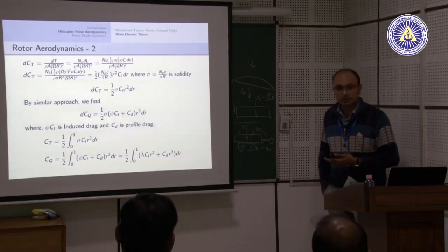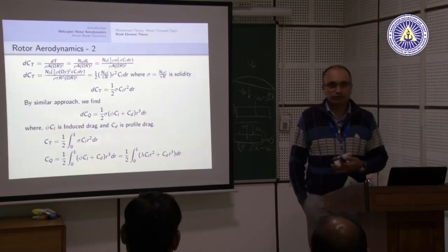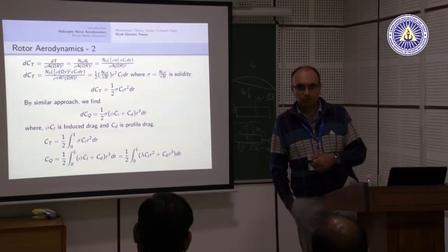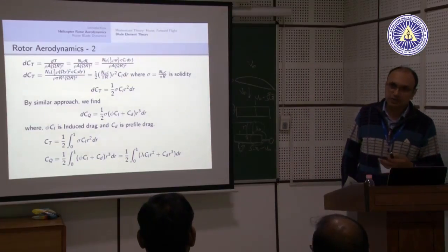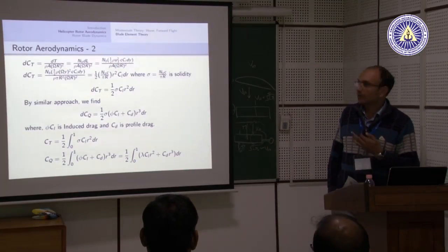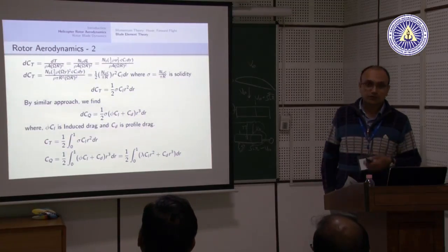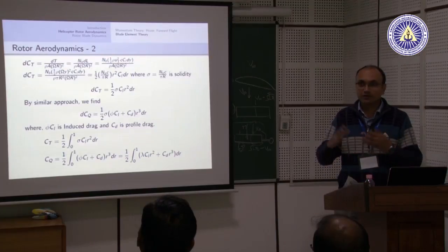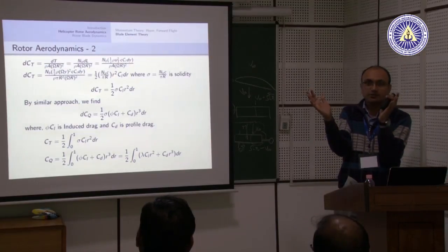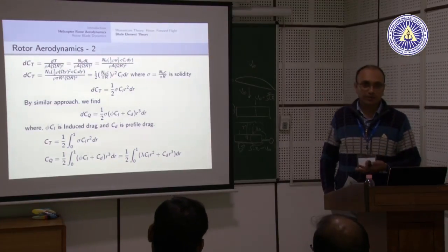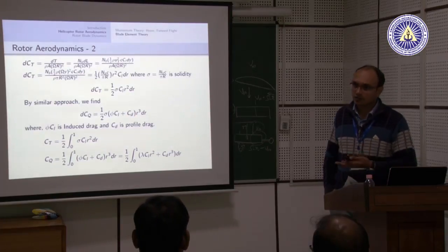It is typically fairly small, of the order of 0.05, 0.06 and so on. Okay. Most of the rotors have low solidity, but if you compare this to a fan, not a ceiling fan, but a table fan, a table fan has typically very high solidity because the blades are short and wide. Even marine propellers normally have very high solidity.